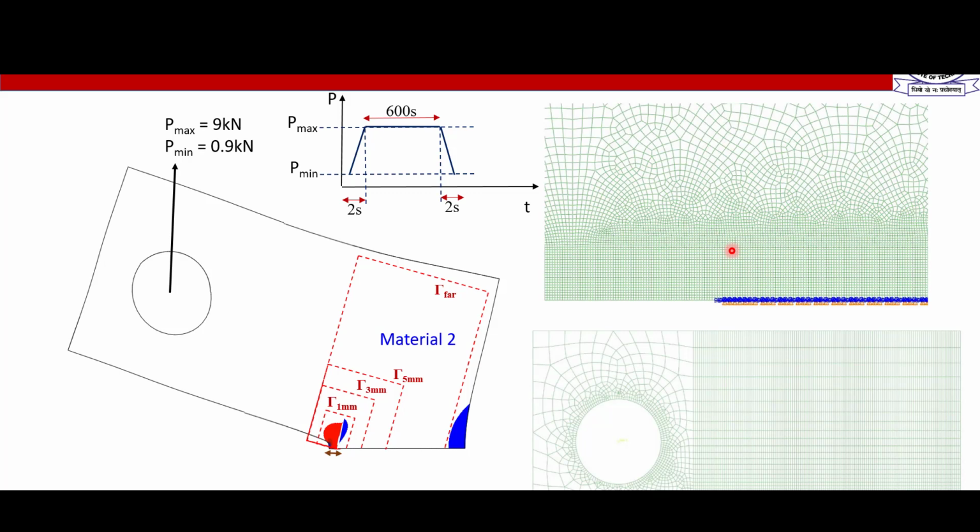Some researchers have a problem with the node release technique, because they think that it is an artificial way of growing a crack, and material may not grow the crack in that way. That is true. But even with artificial crack opening, we will be calculating the correct value of the CT integral. Why not? If the material opens with a dA by dt of some value, then it must have the same value of crack driving forces or the stresses at that value of dA by dt. So even if the dA by dt part is managed in computation, the value of the integrals should not be wrong.